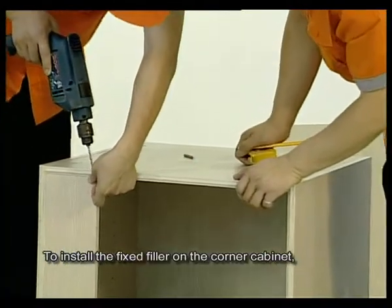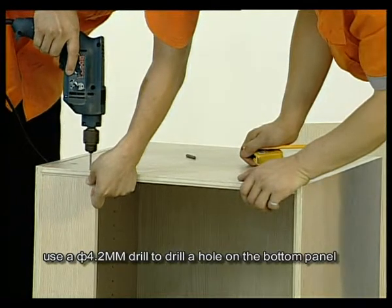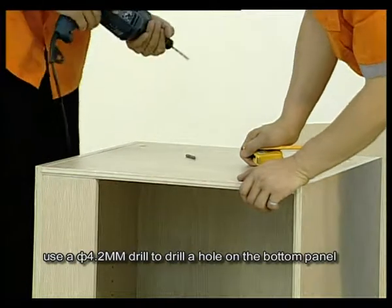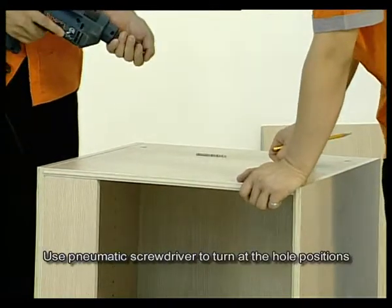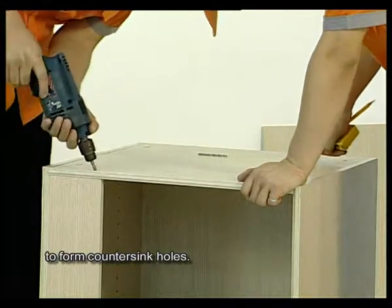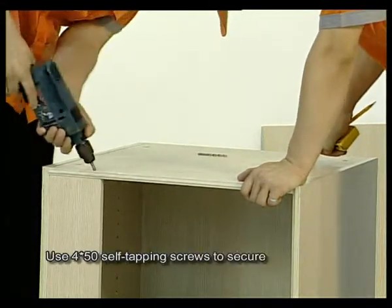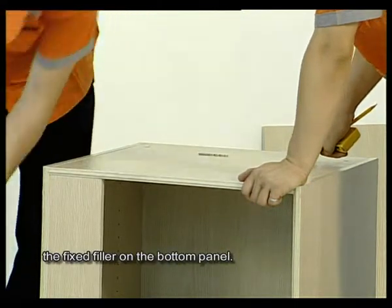To install the fixed filler on the corner cabinet, use a 4.2 mm drill to drill a hole on the bottom panel at a place near the fixed filler. Use a pneumatic screwdriver to turn at the hole positions to form countersink holes. Use 4x50 self-tapping screws to secure the fixed filler on the bottom panel.